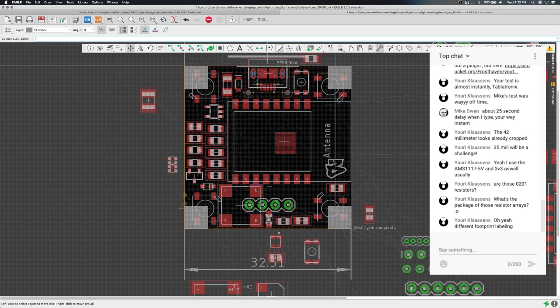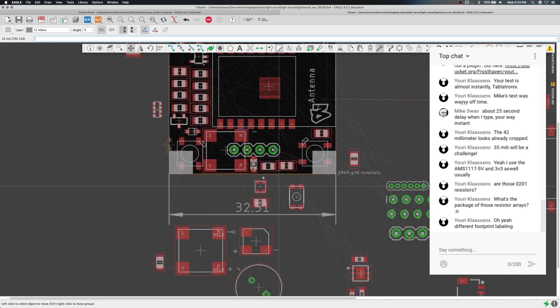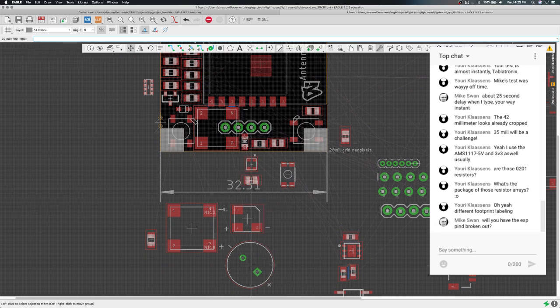And I don't know if I'm going to put LEDs on the back again. Probably are. I'm probably going to put NeoPixels on both sides, if I can get the routing to fit. If I can squeeze the routing in here. Because all this right here has to be blocked out. Maybe I can even cut this out here if I don't use it. I don't know. But I think I'm going to be able to make this fit. Worst comes to worst, I take this piezo off and use an above board through hole.